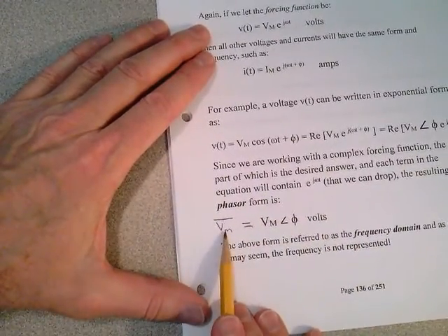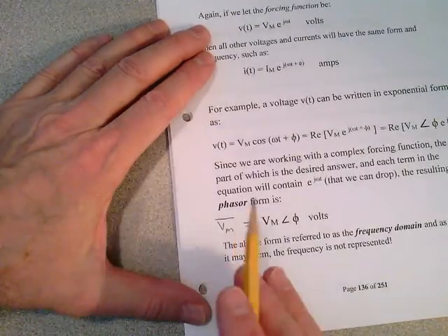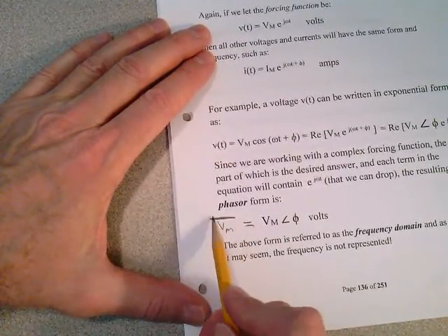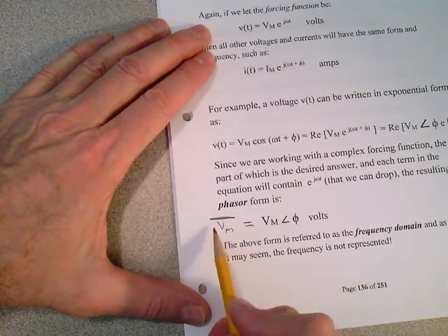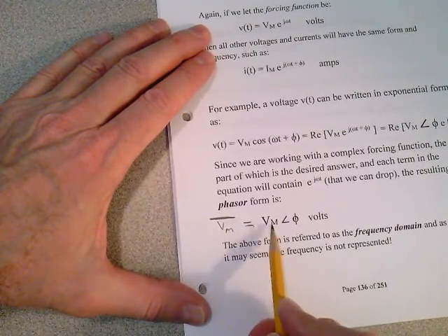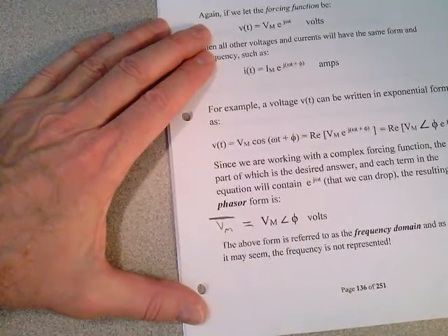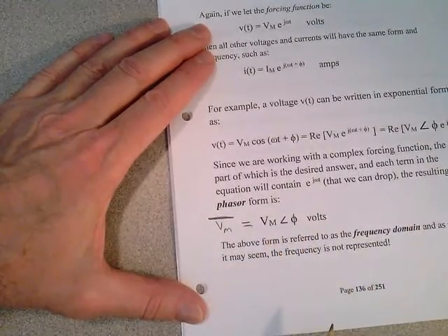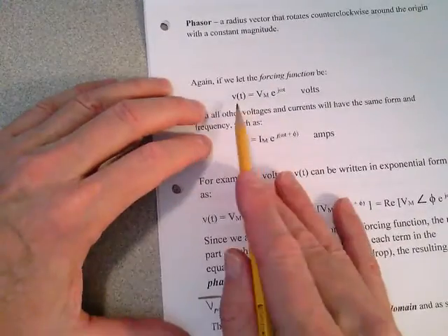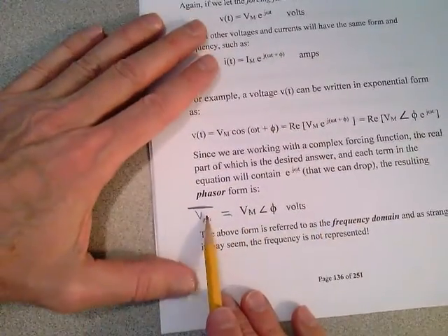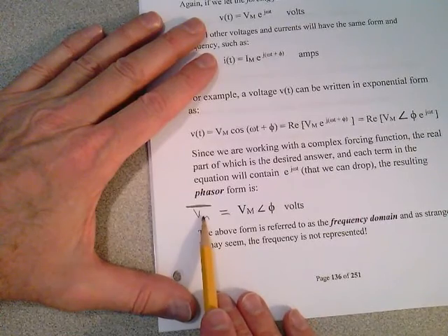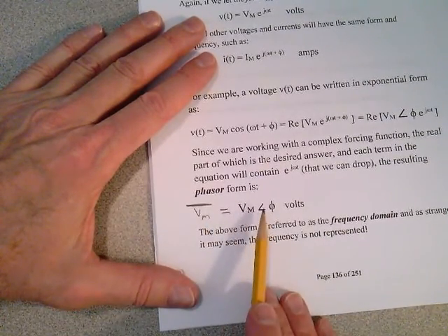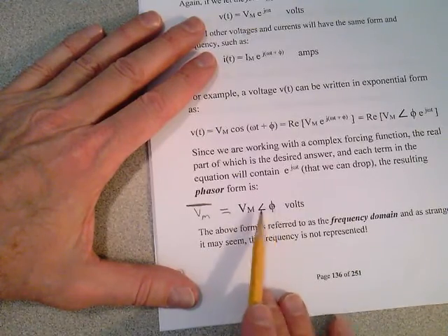which is going to be the vector quantity, v max, in this case Vm, it's a vector quantity. It's going to have magnitude right there. It's going to have a direction right there. So I might refer to this as the phasor form, but to be consistent, I'll refer to v of t as the time form. I'll refer to something like this as the frequency domain or the frequency form. But frequency is not even represented here. There's no omega represented in these phasors.